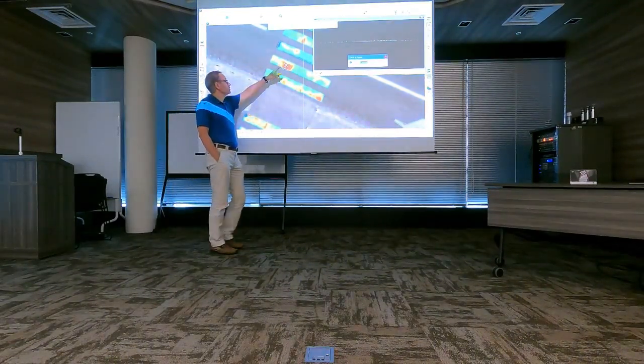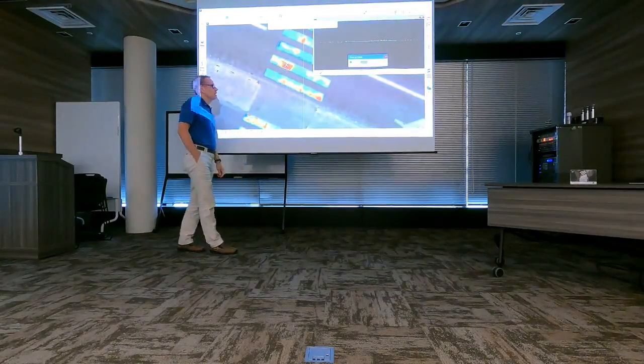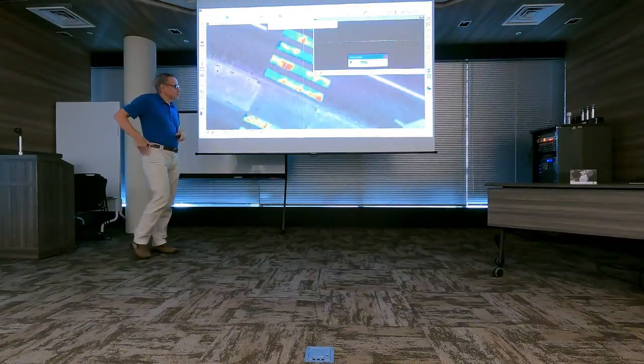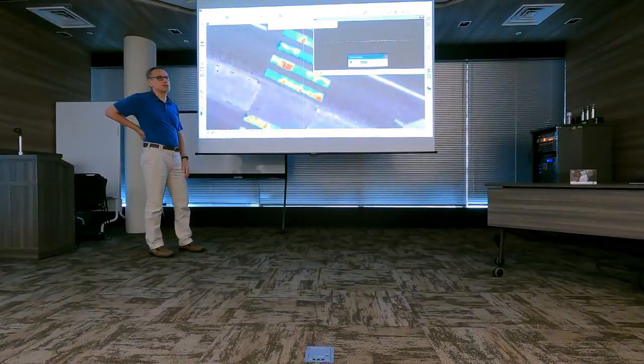When the software computes the distance value for a point at that spot, first of all, it decides a circle radius big enough so that we get enough of the points outside the polygon. And outside the polygon, there is that margin setting in the dialog. I had 1 centimeter of margin. What it says is that we don't use points within 1 centimeter outside of the polygon. We don't use those for computing the elevation of the underlying asphalt.